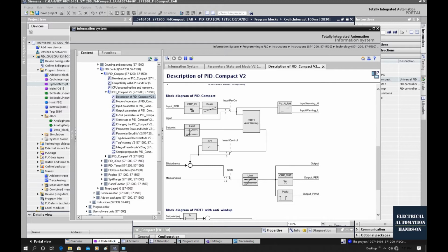And the third channel is a PWM. If you are using PWM to control the motor or the fans of a DC motor, you could use this channel. But based on my experience, in 95% of projects we will use the output only, so the first channel, and unscale the analog output outside the PID.